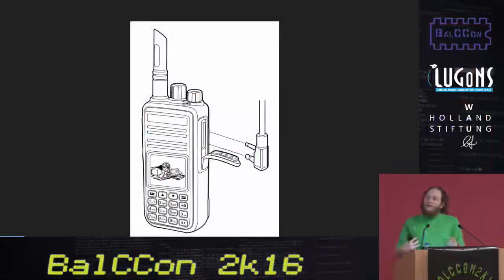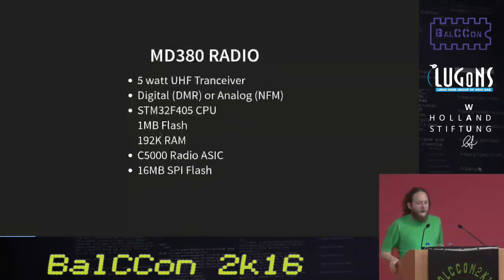When you transmit with this model, it transmits either analog or digital. And you can hit an analog repeater or a digital repeater, and through the digital repeater you can send compressed audio using half of the time slots. So you can have two conversations on the same radio repeater.